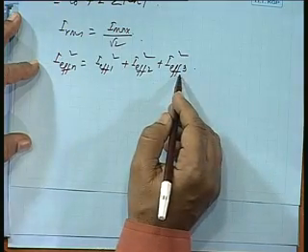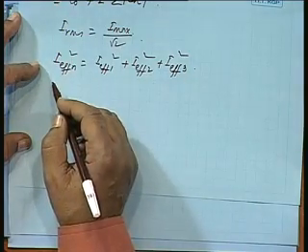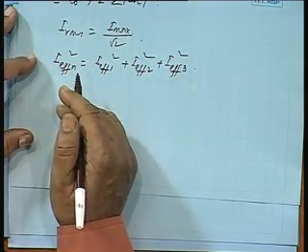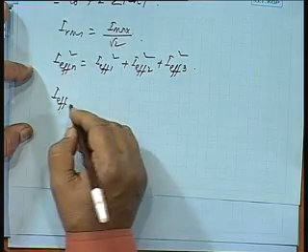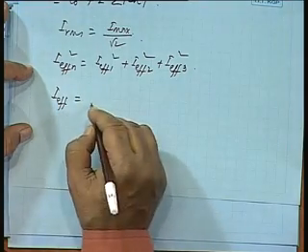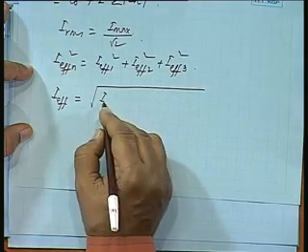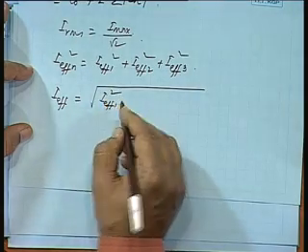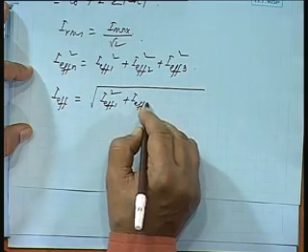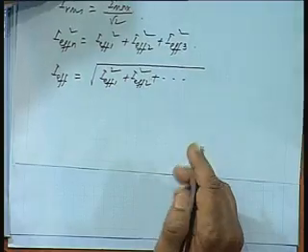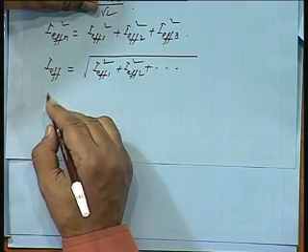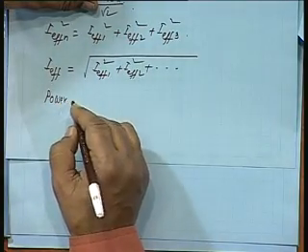That is, if you have a harmonic rich signal and you want to find the power spectrum, you take each harmonic and the corresponding effective values, square them up, and the addition of that will be the overall effective value squared. So I effective will be the square root of I effective 1 square plus I effective 2 square and so on.